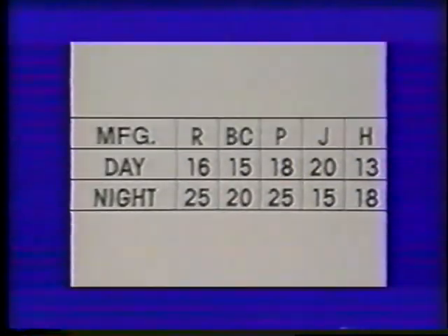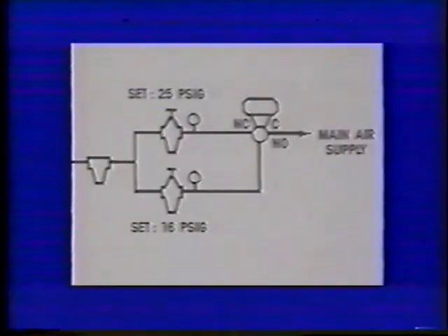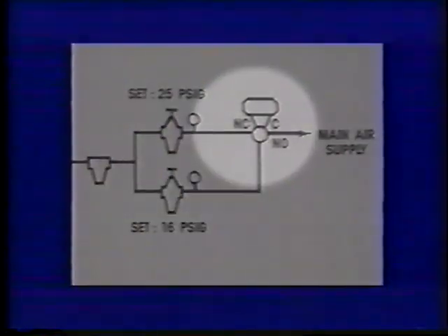The two main air signals from the pressure-reducing valves are supplied to a three-way air valve before going to the thermostat. This three-way valve is switched, either manually or automatically, to provide the appropriate air pressure to the thermostats in the system.